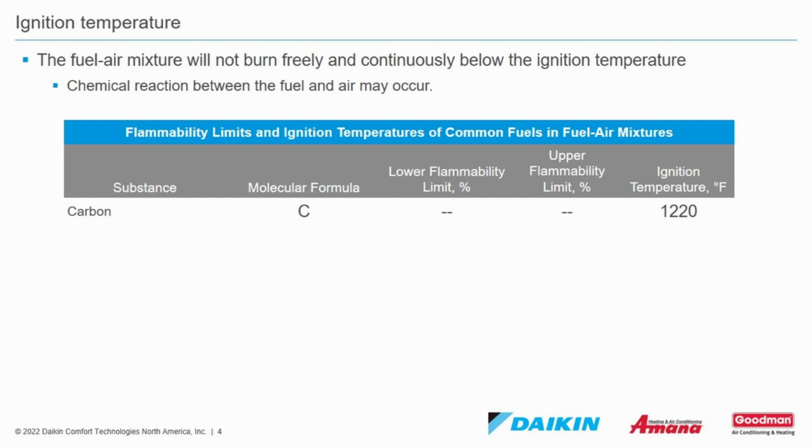Carbon, molecular formula C. There is no lower or upper flammability limit in percentage. Ignition temperature, 1,220 degrees Fahrenheit. Carbon monoxide, molecular formula CO. Lower flammability limit, 12.5%. Upper flammability limit, 74%. Ignition temperature, 1,128.2 degrees Fahrenheit.